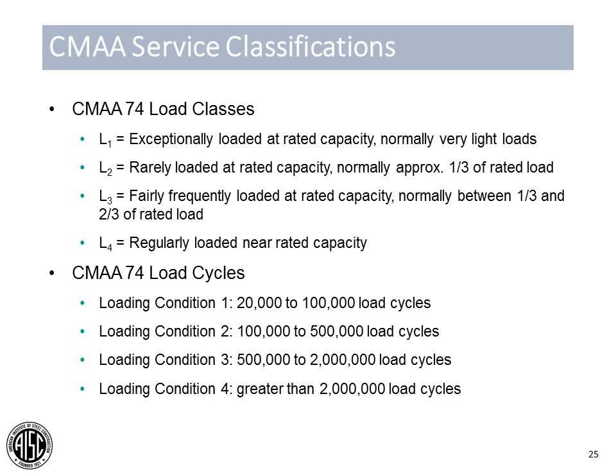And then also how many load cycles are anticipated. This is the number of picks that are made per shift times the number of shifts per day times the number of days in the entire life cycle of the crane. So this is an estimate used generally at the beginning of the design phase based on the owner's experience in most cases.